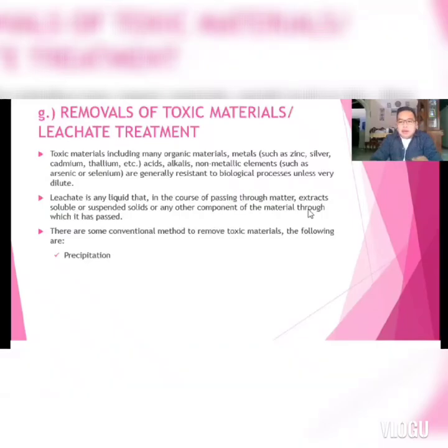And now, let's tackle ion exchange. Ion exchange is another method used successfully in the industry for the removal of heavy metals from effluents. Though it is relatively expensive as compared to other methods, it has the ability to achieve ppb levels of cleanup while handling a relatively large volume. An ion exchanger is a solid capable of exchanging either cations or anions from surrounding materials.